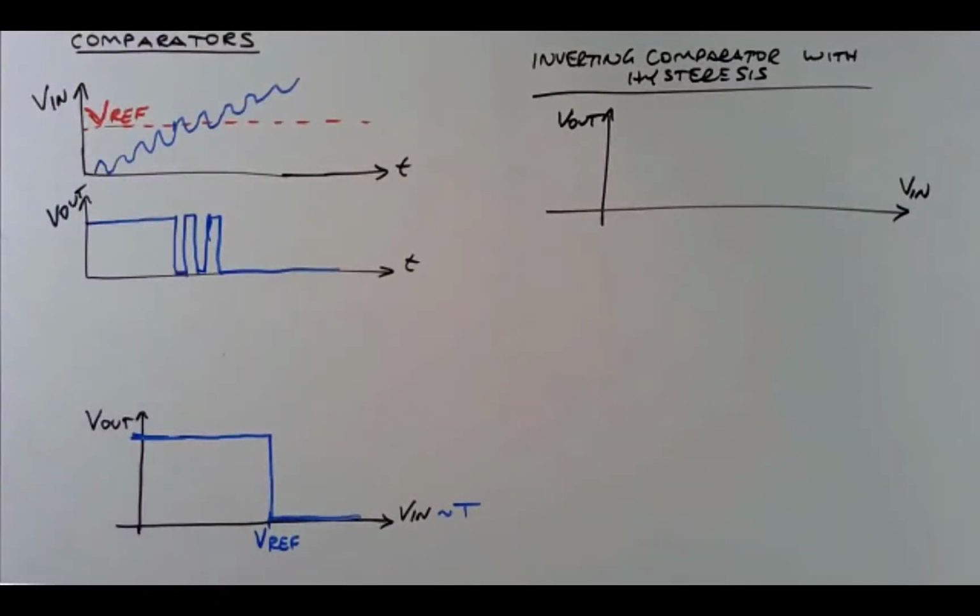And this is how your thermostat in your house, your apartment, your condo really works. If you notice, your heater doesn't turn on and off every time the temperature varies by 1/100th of a degree, right? Let's say your house is cold, you turn the heater on. It typically warms the house up to, make up a number, 70 degrees Fahrenheit. And then the house might cool down a little bit, maybe a degree, 69 degrees Fahrenheit. And then the heater turns on. But it's not like the heater's turning on and off every 2 seconds as the temperature varies 1/100th of a degree. So that requires 2 thresholds.